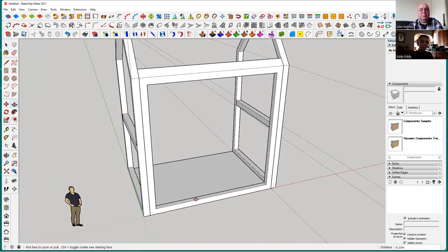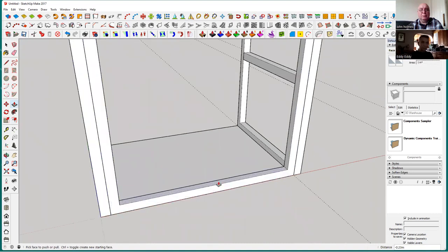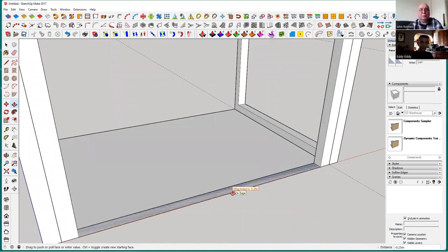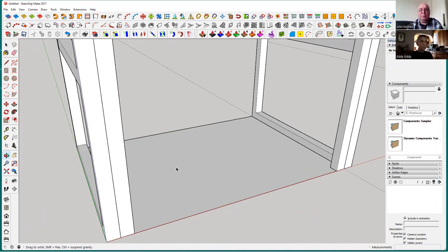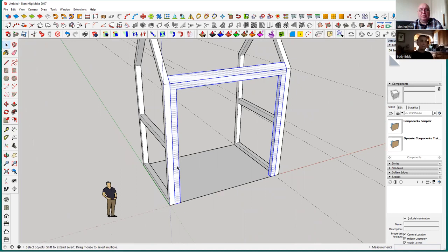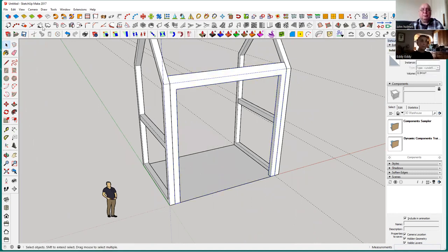And because we normally have doors front and back, if we pick this bottom edge, push it down until the offset limit is reached, front wall disappears. We get our pick tool. These are stray lines now. Delete. And there'll be another one at the front. Delete. Triple click to highlight our front frame wall. Make a group. Save.